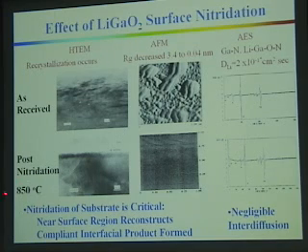However, if we nitrided the surface by exposing it to ammonia at an elevated temperature, in this case 850 degrees C, you see that this region near the surface recrystallized and became single crystal. You'll see the surface smoothed to essentially a specular surface. And according to this Auger spectra here, you'll find that there's nitrogen content after nitridation.